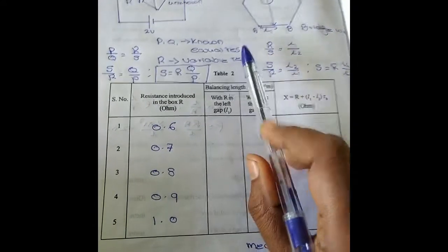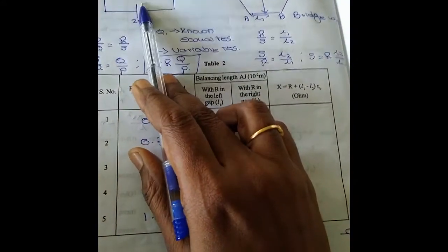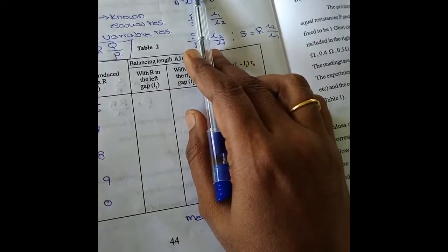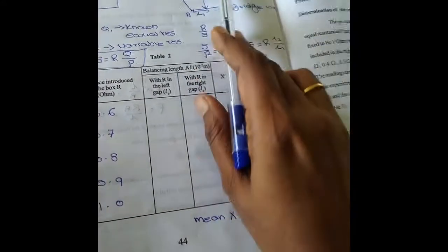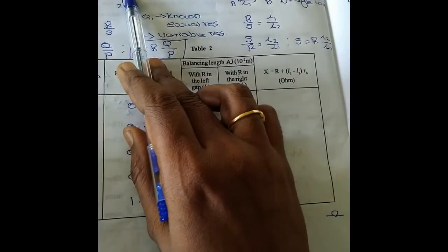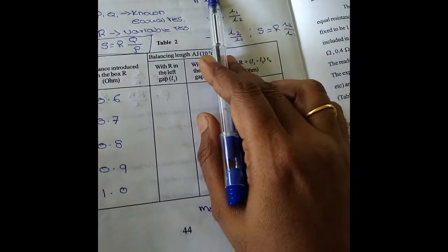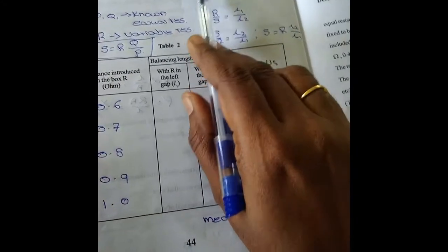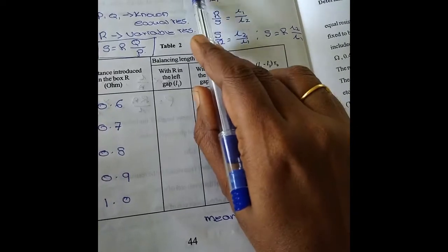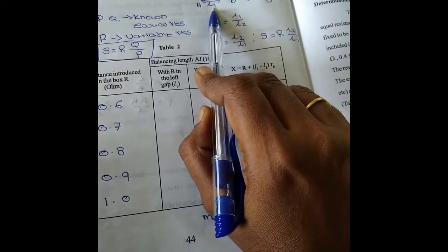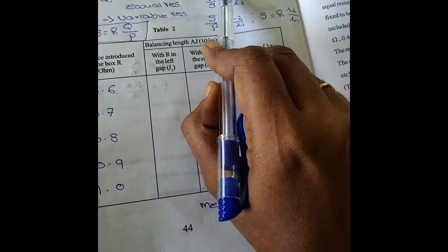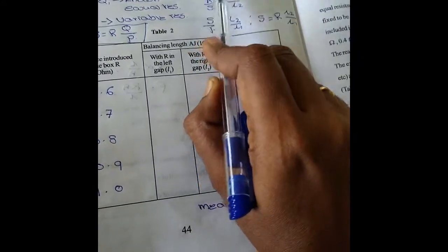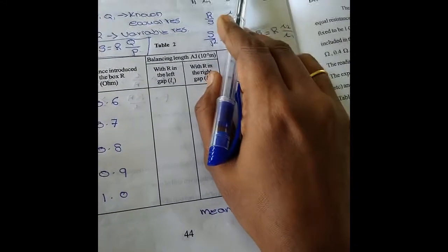This is what we call a Wheatstone bridge, and this Wheatstone bridge is utilized in the meter bridge to determine the unknown resistance. And this Wheatstone bridge was modified a little by Carey Foster, and the bridge was known as Carey Foster's bridge. What he did was include two resistances here and here so as to decrease the potential drop along the length of this wire, and that increases the accuracy of the unknown resistance value.